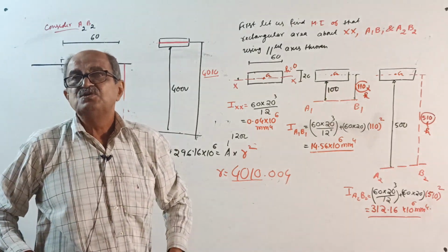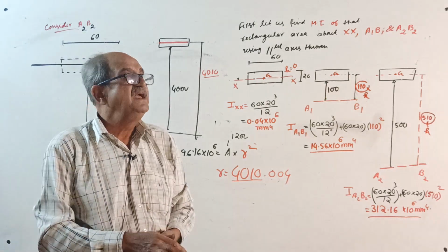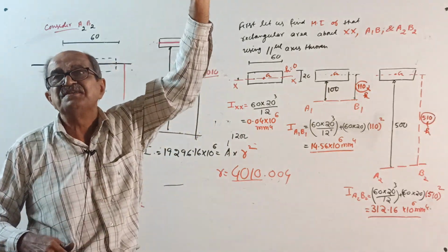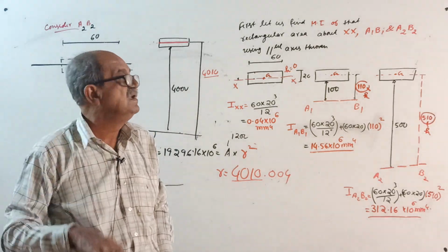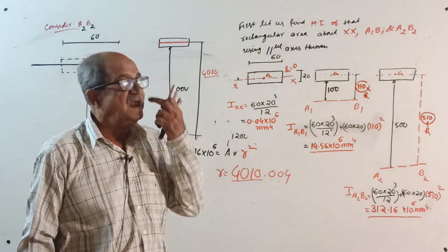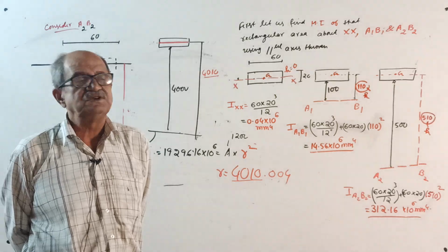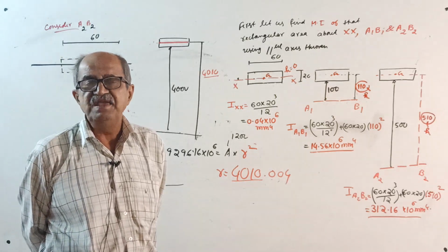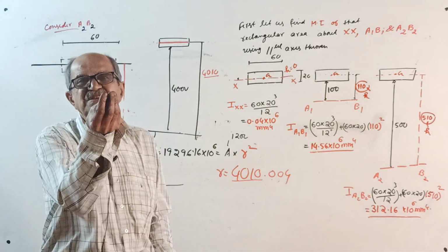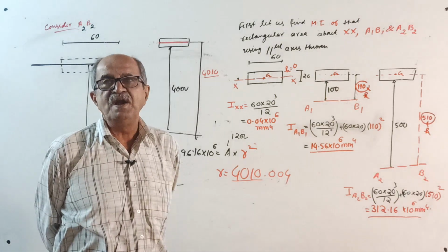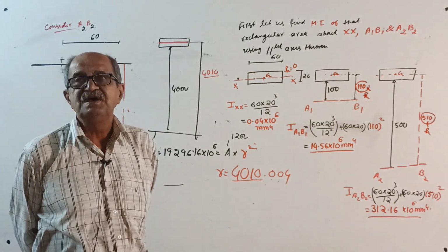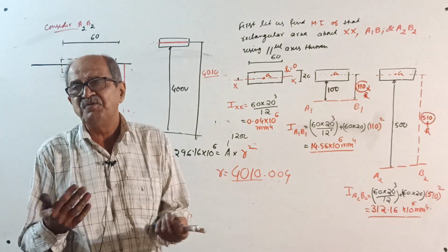That is why, many times in structural engineering, if the area is dispersed at a very high distance, I will tell you how high you should decide; that is logic, or your judgment at that time. Then, instead of using Ig plus A h square, people will directly calculate I equal to A h square. They will ignore the term Ig, because Ig is so small. It is like 15, 20 rupees added to 35 or 40 crores. Who will bother about 15, 20 rupees?